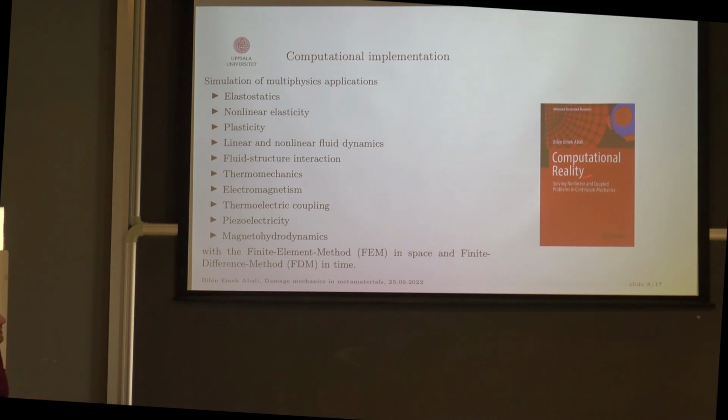This book has the really standard stuff like elasticity and plasticity, and also the code. So it's not only the textbook information about elasticity, but you also see the code. Not only the textbook information of plasticity, but you also have the code in it. And there is also a little bit more. If you are interested in the coupling of thermomechanics and electromagnetism, you can find all the theory first and the code afterwards. Then you can immediately see how easy it is: just write 100 lines of Python code in FEniCS and get the job done. Once you did it and you want to change the material model, it's just one line. And if you want to use commercial software, then it's maybe a really tedious task.